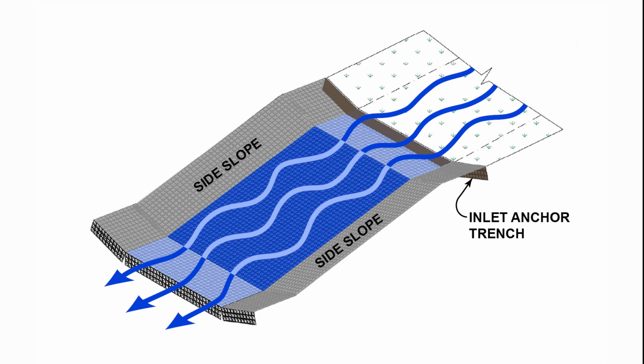Finally, the water will exit the chute structure, crossing a 13-foot outlet apron into the ditch. This outlet apron acts as a splash pad to dissipate the energy of the high-velocity water exiting the chute. The outlet apron, like the inlet apron, is also keyed into the existing ground using a 24-inch trench. This downstream key adds some protection to hold the structure in place in case the downstream ditch becomes lower than expected for any reason.